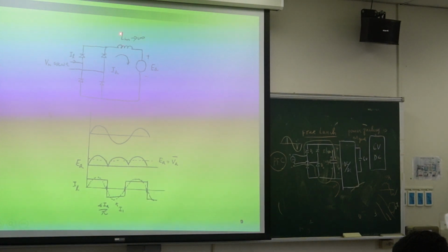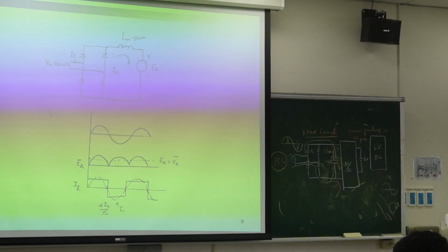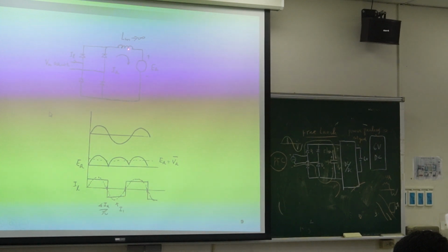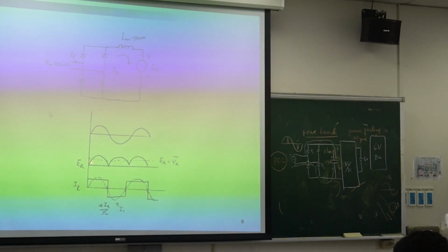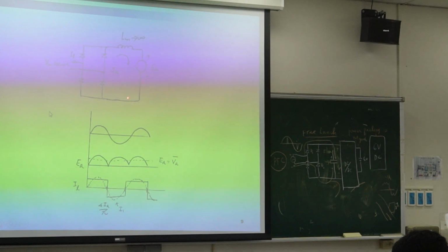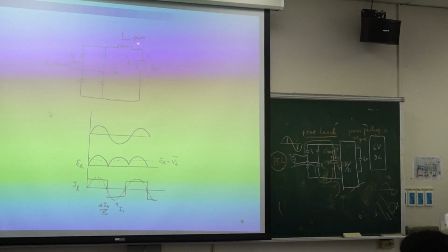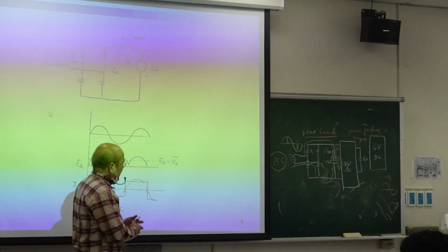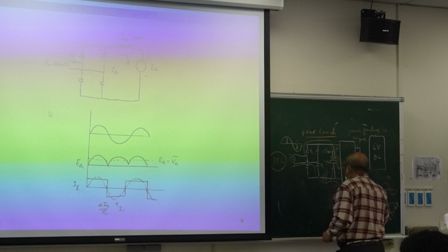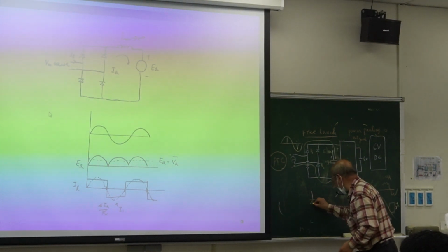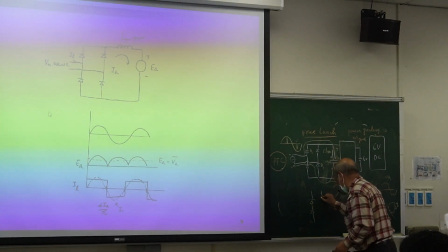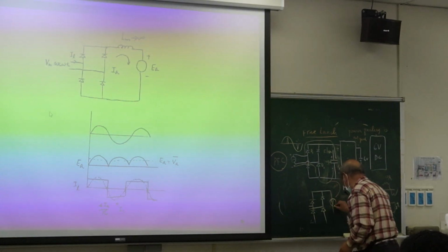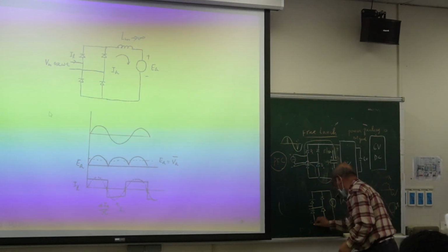Can I replace the capacitor with an inductor? Right? Very simple, right? So I use an inductor, a large inductor here. So if we turn on the diode, then the inductor creates constant current, right? The inductor creates constant current. Then what happens? Then we have a circuit. If we put a huge inductor, then the output becomes constant current. So like this.